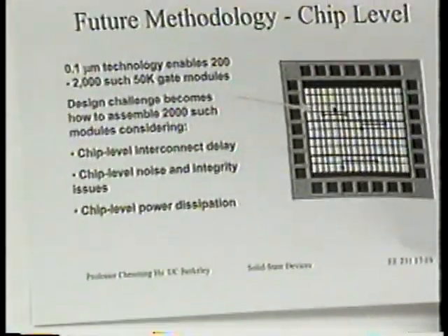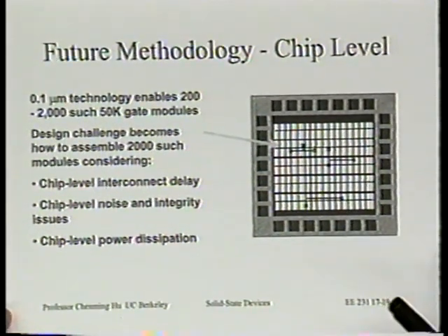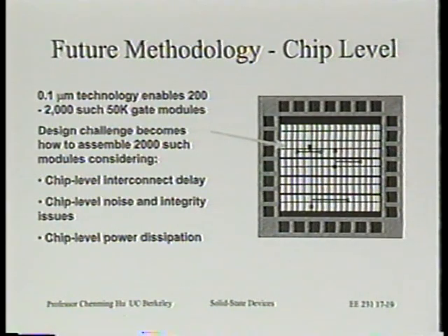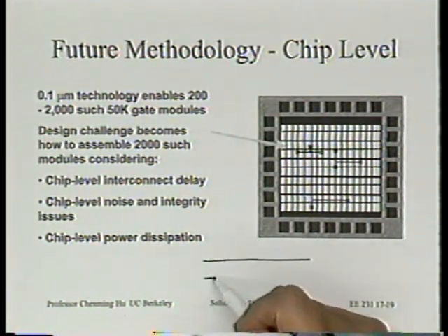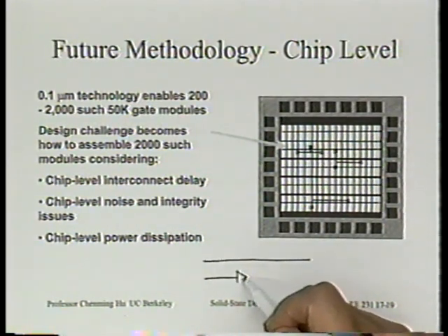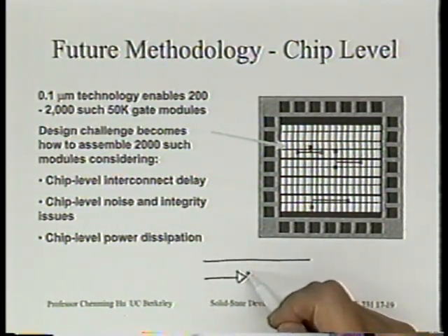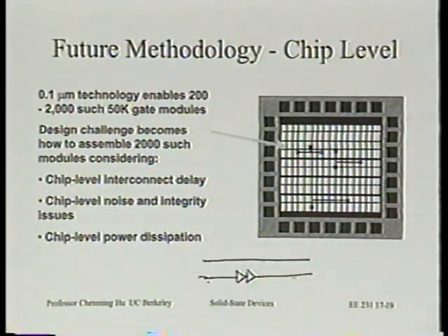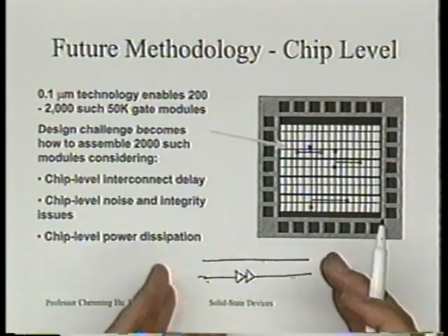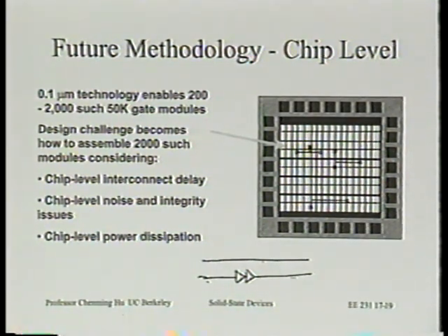the potential things that people can do will be things like optimum, let's say, buffering devices, stages. Turns out the delay time is a little shorter if you break one large interconnect to two interconnects with an amplifier in between, all right? And this has a smaller delay than that interconnect. So depending on the length of the interconnect, you may even break into two.